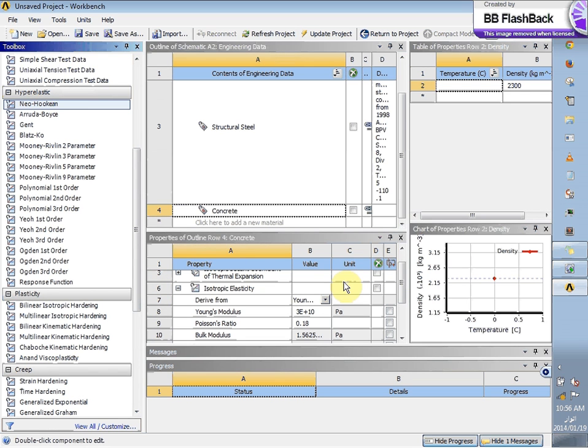too. And you can change those properties, and now concrete will also, if you change those properties, start showing foamy behavior too, whatever you add in there. So you are creating new materials too. This is called material modeling. The structural modeling in SAP you have done already, how to create brick, how to create mortar. This is called material modeling, and this is how we can do it very easily in Ansys. You can mix and match different properties together. You can create new types of materials.